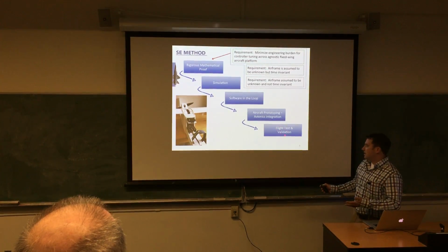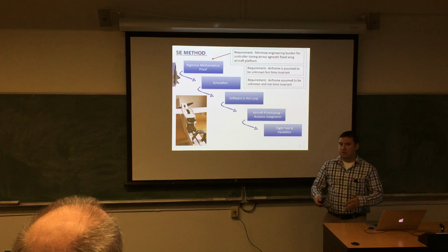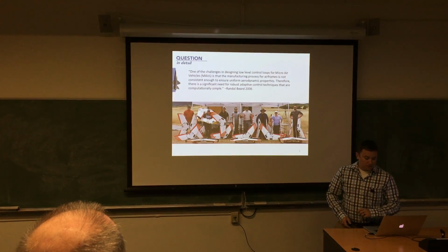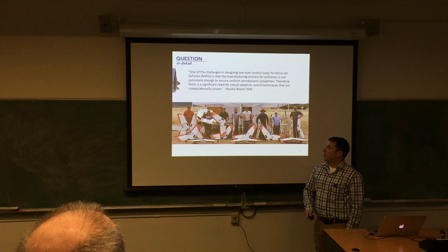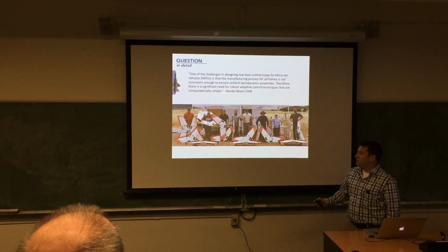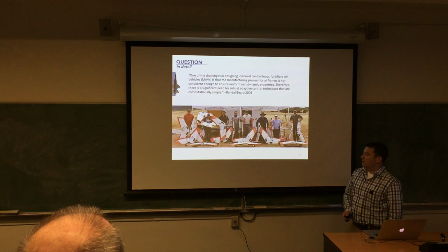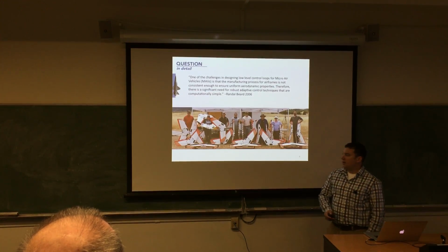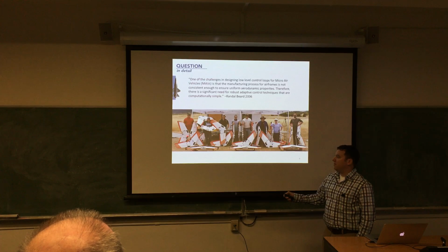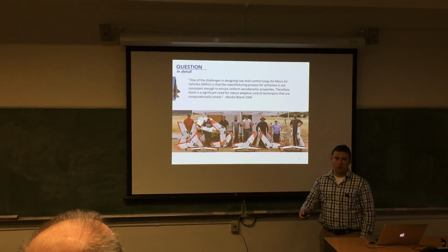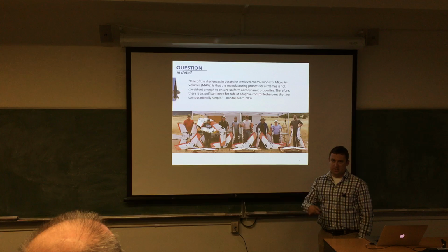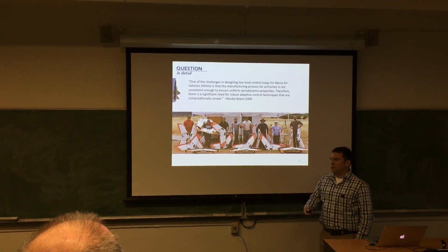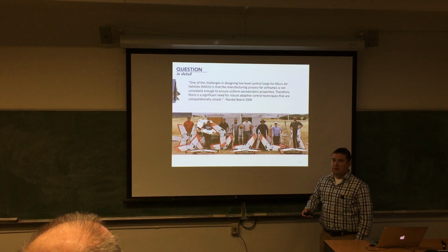And then finally, what you're looking for is flight test and validation. If you can get to flight test and actually prove it in actual flight tests, your credibility goes up. So that was the ultimate goal. Fortunately for me, early on in my time at NPS, I was fortunate enough to help in some of the flying of the NPS swarming aircraft. And what I quickly realized was that all these aircraft are made by the same manufacturer, right? So you can just tune one controller, use a conventional PID controller because the airspeed's not changing, and make all these assumptions. Well, that's actually not true.